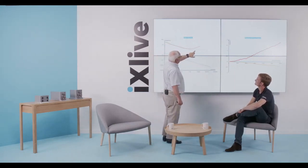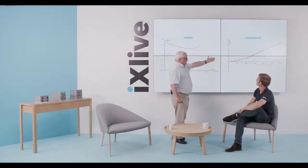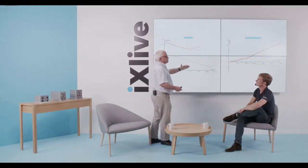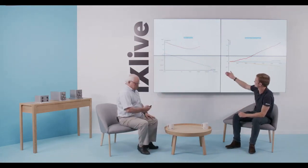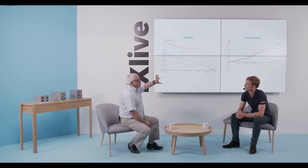And for the yellow one, the minimum value is very similar, but it's much more stable. This is what we see here. And this one is very, very low, and so this is why here we have a quasi-perfect heading drift situation. We should wait for a longer term to see the drift of this sensor. I think an important notion to tell here is that this is a lab result. And by the way, all these measurements were made with lab measurements of the gyro.